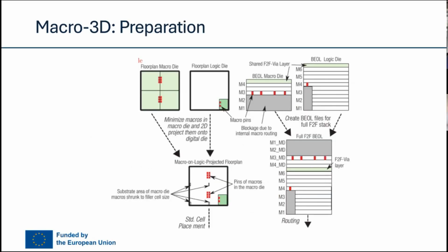The next step that we need to execute this flow is the generation of dedicated IPs. If we, for example, think in terms of the implementation of memory elements in the top tier, you will see that by implementing there, the location of the pins is not going to be in the original metal 3, but in another layer according to the F2F full stack.